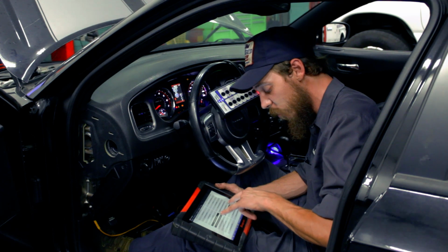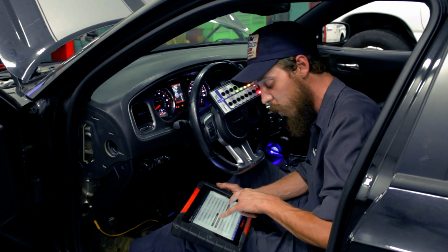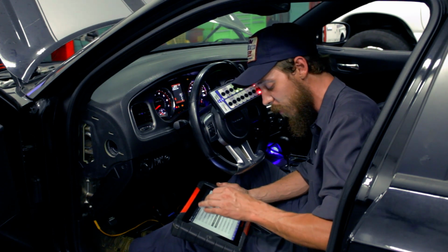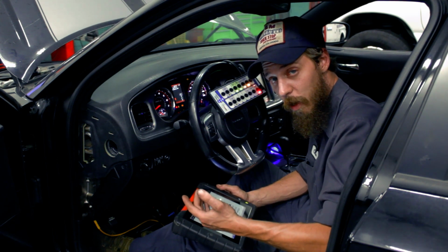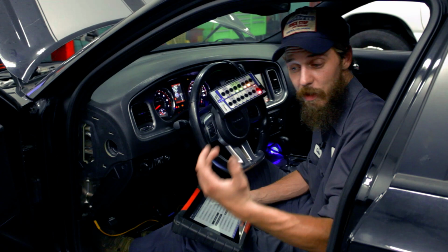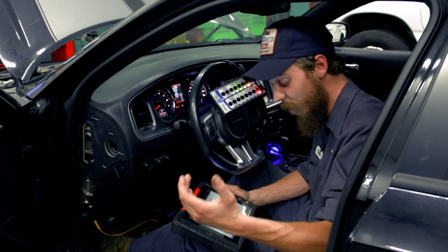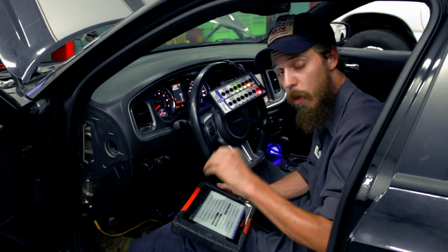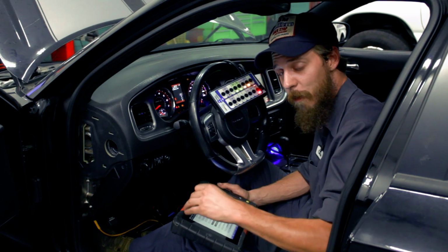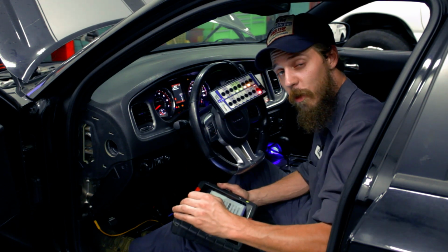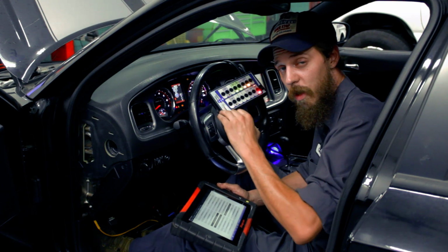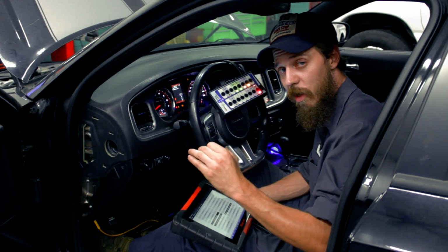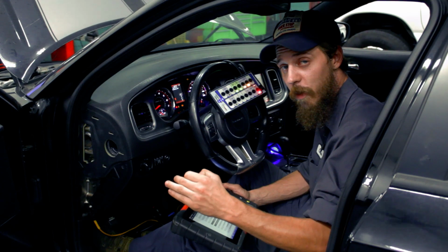Notice how we have two data PIDs here that are transfluid temp, reverse or drive only, degrees Fahrenheit, and what appears to be a duplicate data PID of that. As I just said 45 seconds ago, in park or neutral, the transmission temperature is a substituted value taken from the engine coolant temperature sensor reading. So it is an indirect reading as well as being a substituted value.